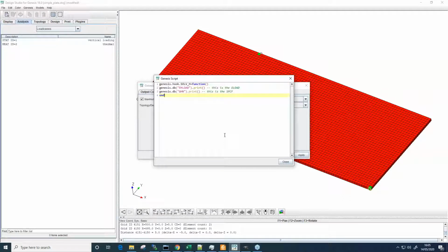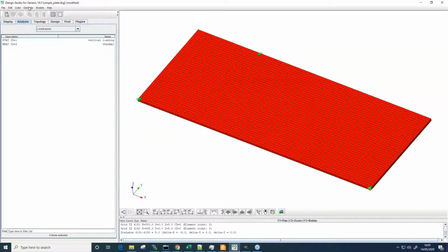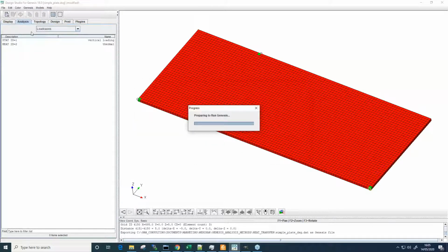These are actually remarkably powerful features in Genesis, where you can write all sorts of output. You can get the analysis solver to be writing your Excel spreadsheets of all your report analysis results if you get into it a little bit more. Very powerful functions to save you post-processing and just generating reports directly from the solution. But in this case, we're outputting this data object here, which is essentially our heat fluxes at all of the nodes. So I'll request those, and then we can do our thermal solve.